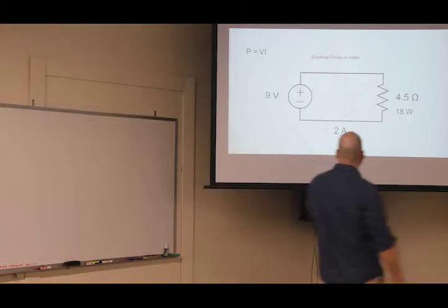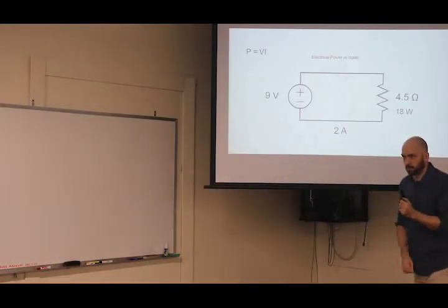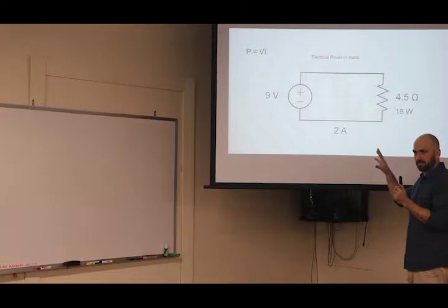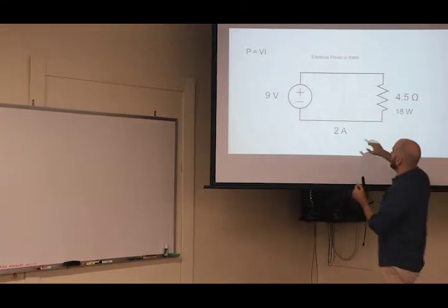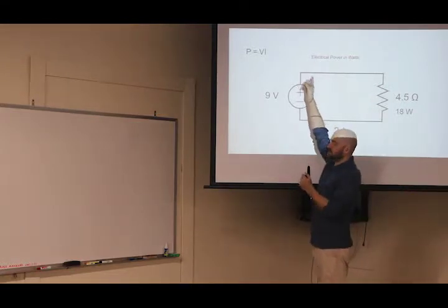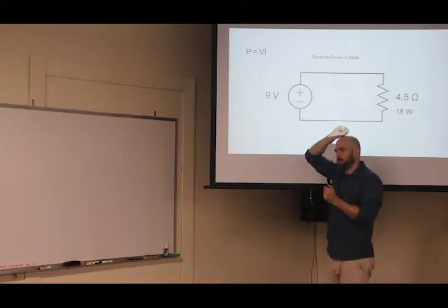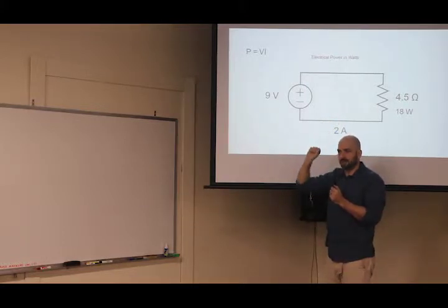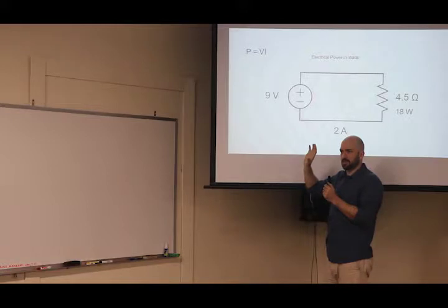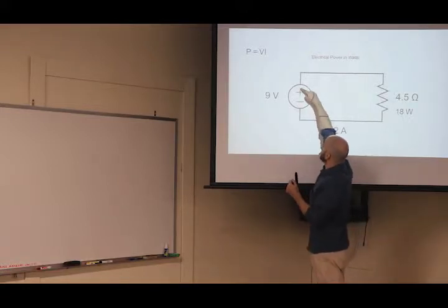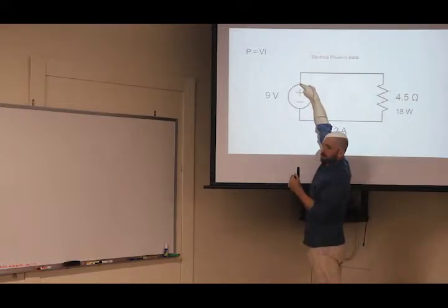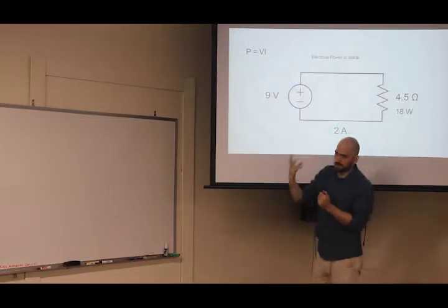Okay. The question was 9 volts going through the resistor. Where is the 9 volts? Is that right? Yeah. So this whole section, you can think of a wire as an equipotential. That's the node in that network that we showed earlier. So this, right on the voltage source, is guaranteed 9. That's what the voltage source is doing.